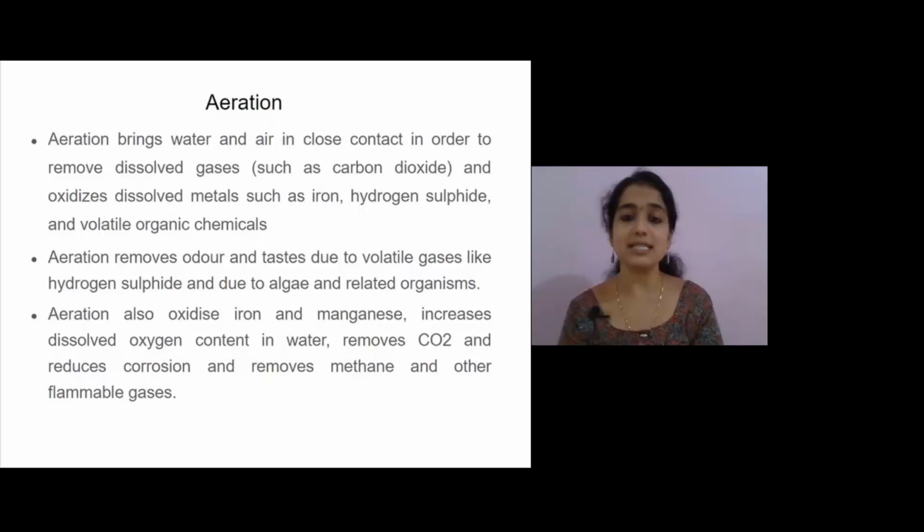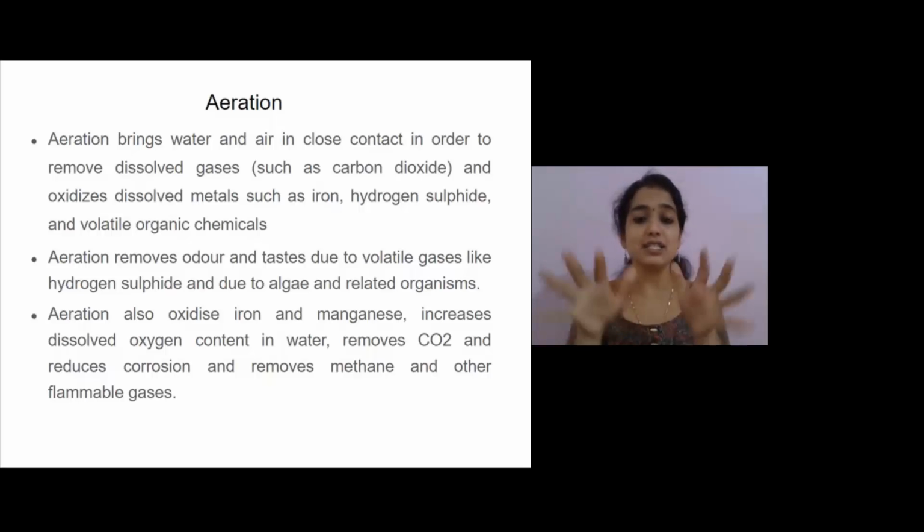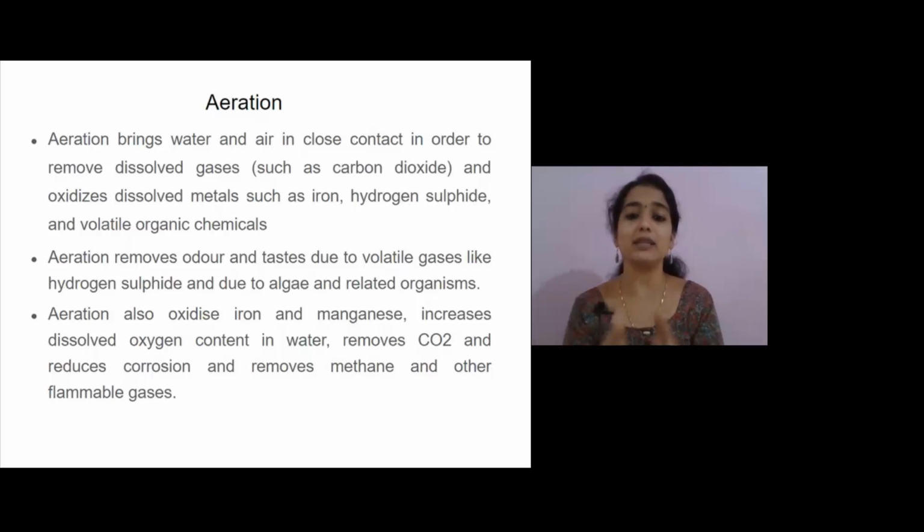Aeration also oxidizes iron and manganese, increases dissolved oxygen content in water, removes carbon dioxide and reduces corrosion, and removes methane and other flammable gases. The dissolved oxygen content in water is very much important in the case of aquatic life. So we have to improve the dissolved oxygen content present in the water, and for drinkable quality of water we have to have a minimum quantity of dissolved oxygen present in water. So the aeration process is very much important in the water treatment process.